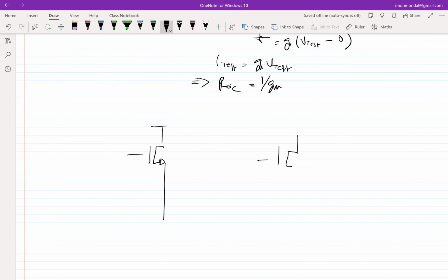So you have this transistor. Let's say you have this transistor, right? In the incremental sense, if I look in through this and we short this, I get 1 over GM impedance. Correct? In the incremental sense. Here, even though I get infinite impedance, it's useless because I cannot draw any current. What happens if I look from here? How much impedance do I see? Looking from the drain, do I get 1 over GM?